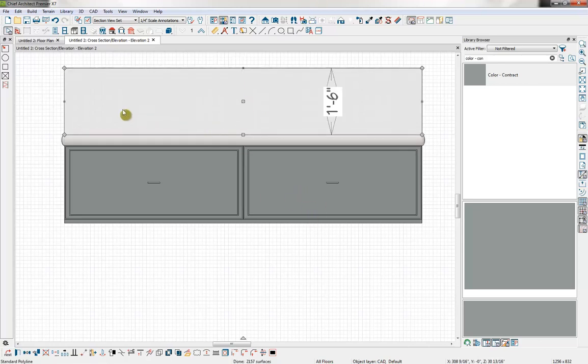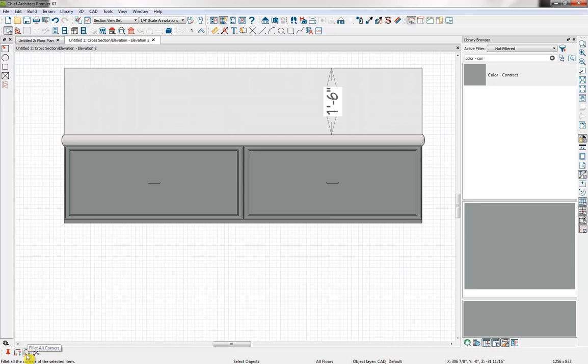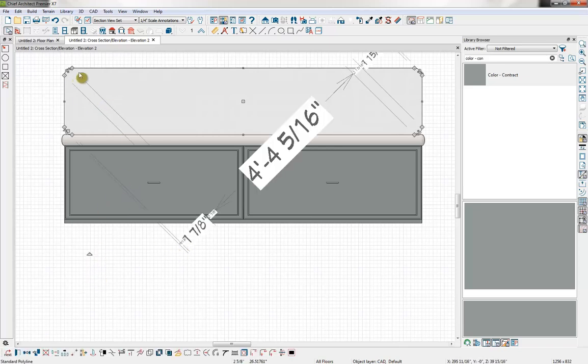So next I'm going to want a little bit more rounded edges here. So I'm going to go to the fillet tool. When you click on fillet, you now have some additional options down here. One is set the fillet radius. Now I have it at 2 inches here, and that's what I want to keep it at. So I'm going to click enter, and then I'm going to use the tool Fillet All. Now Fillet All rounds all the corners, and then I'll just click enter, and that has returned me back to my normal edit tools, and I have rounded edges on all of the